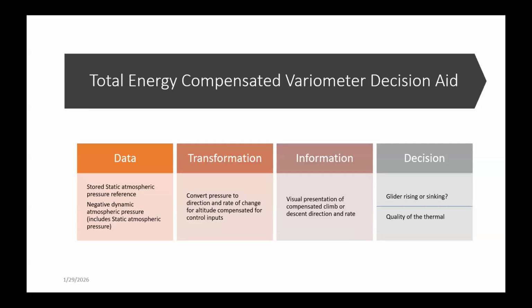polar. So for instance, if you're flying at 82 knots in calm air, I think this is from my Ventus, I should expect to see 4 knots down indicated. If you're circling at a constant airspeed, the TE and uncompensated varios will have basically the same indication.